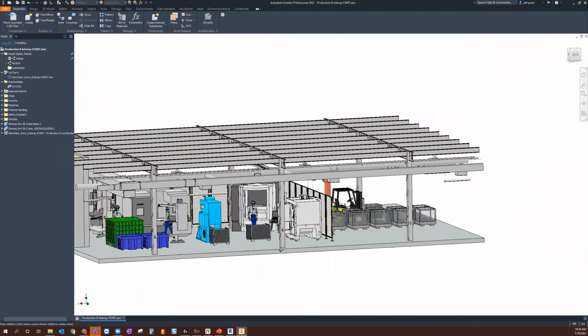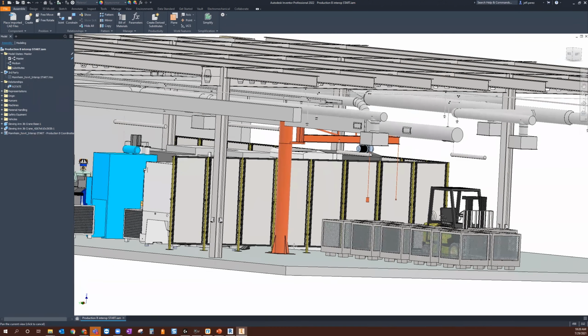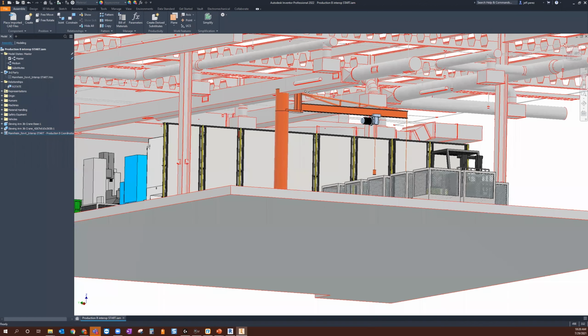And as I'm panning over here, what I'm noticing right away is I have this clash that's happening with this crane. Okay, so hopefully you can see this clash happening with this crane and this piece of mechanical ductwork right here. Now, maybe during this design phase, or during this initial process of coordinating with the architect, it's been determined that the manufacturer is correct in terms of its placement. It's going to really require the duct or the mechanical firm to adjust and move that ductwork so that we're not having a clash with this crane itself.